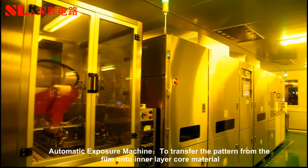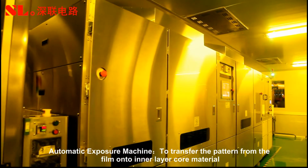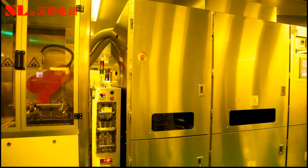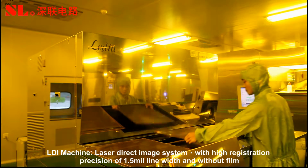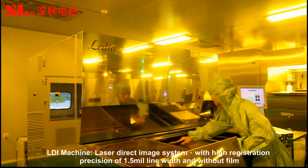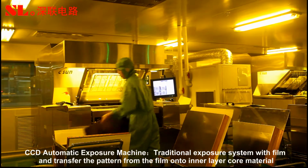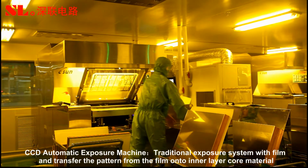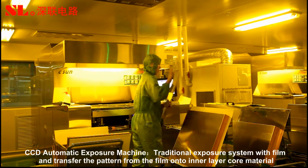Automatic exposure machine. To transfer the pattern from the film onto the inner layer core material. Laser direct image system with high registration precision of 1.5 mil line width and without film. CCD, automatic exposure machine. Traditional exposure system with film and transfer the pattern from the film onto inner layer core material.